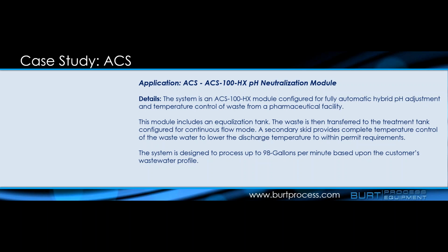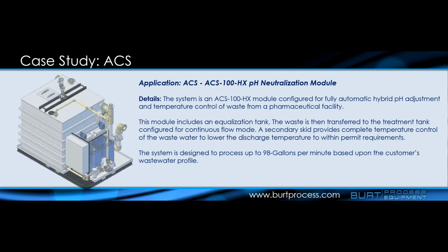And I mean, you're talking about things like steam condensate. If you have things like that getting dumped down the drain, you're going to be using hot water sanitization for your system or cleaning chemicals. Those may be coming in at 185 degrees up to 200 degrees. You do need to control the temperature as part of your wastewater treatment system.